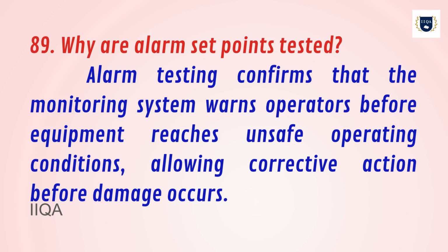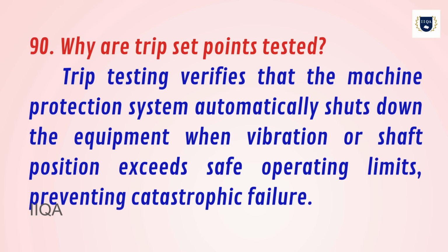89. Why are alarm set points tested? Alarm testing confirms that the monitoring system warns operators before equipment reaches unsafe operating conditions, allowing corrective action before damage occurs.